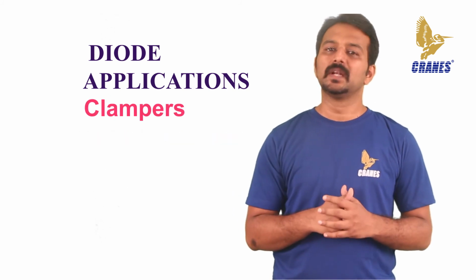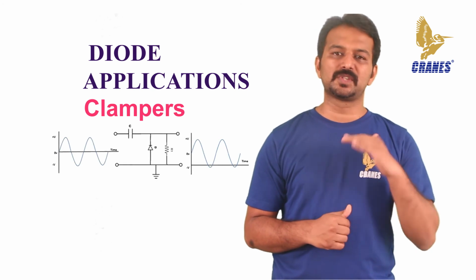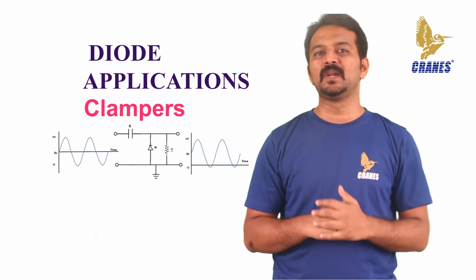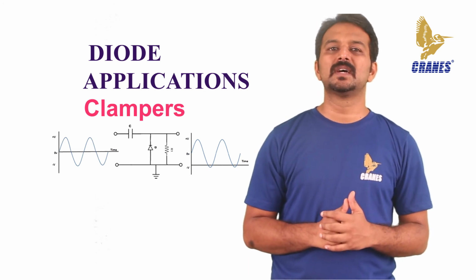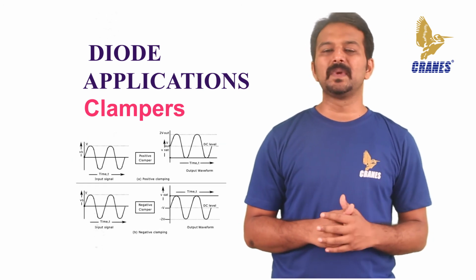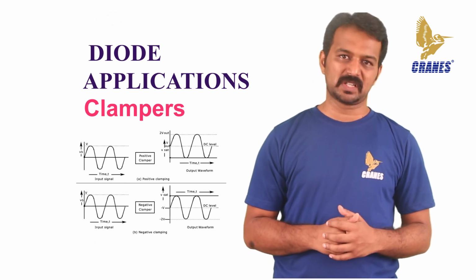So the next one is diodes in clamping circuits. A clamping circuit is used to shift or alter either the positive or the negative peak of an input signal to a desired level. This circuit is also called a level shifter or a DC restorer. These clamping circuits can be positive or negative depending on the diode configuration.